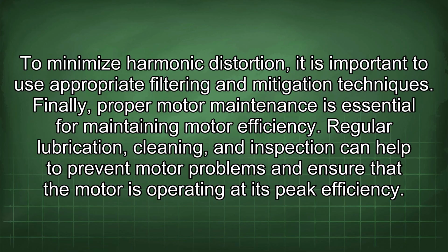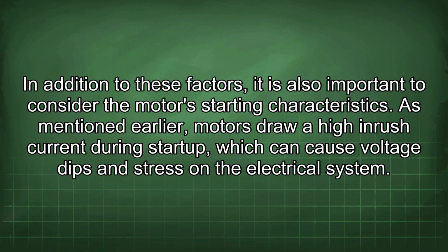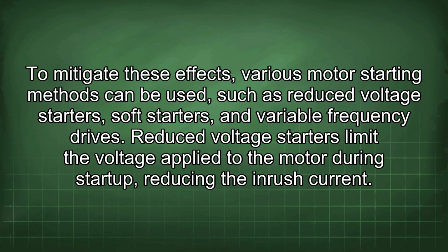In addition to these factors, it is also important to consider the motor's starting characteristics. As mentioned earlier, motors draw high inrush current during startup, which can cause voltage dips and stress on the electrical system. To mitigate these effects, various motor starting methods can be used, such as reduced voltage starters, soft starters, and variable frequency drives. Reduced voltage starters limit the voltage applied to the motor during startup, reducing the inrush current.